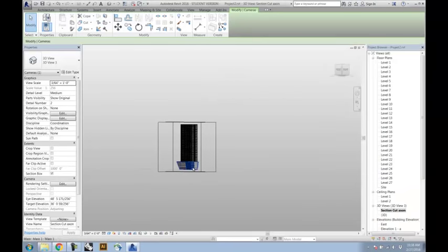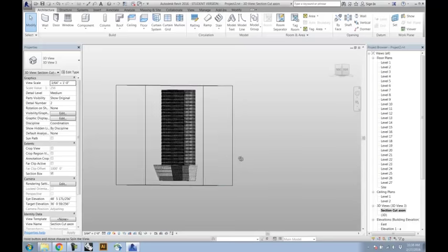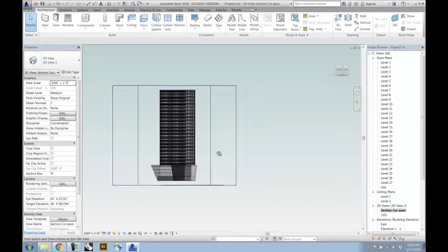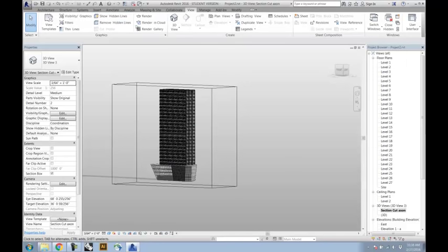You can always adjust this stuff in Photoshop afterwards, but at the same time, it's really helpful to get the view roughly approximate to the photo before you get into it. So just roughly, using some of the materials that you've already defined, if you go back into view, here are the buttons for rendering out a three-dimensional view.